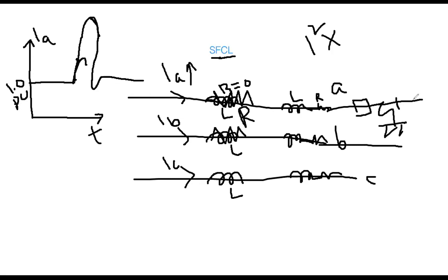And then, for example, when a fault happens, the circuit breaker along the line gets opened to disconnect and remove the fault. That circuit breaker will automatically open within 5 seconds. Now see the line. One circuit breaker opens, meaning that in this line current is getting zero. No current is flowing.